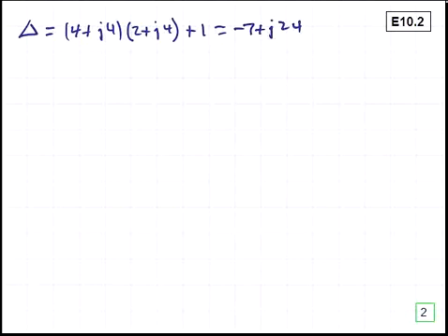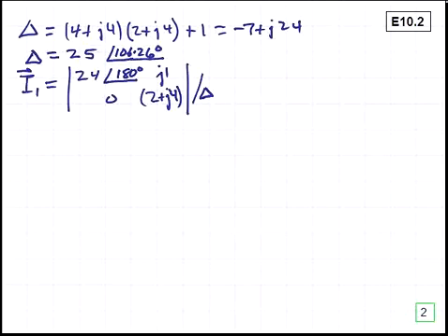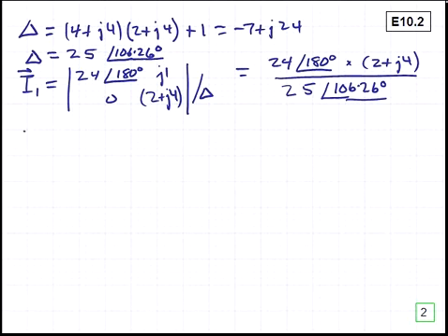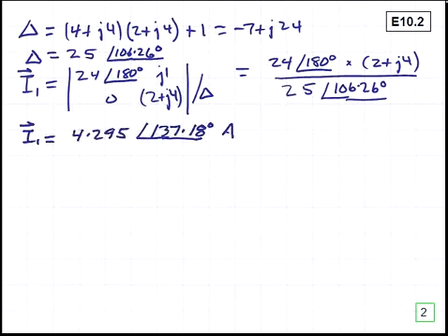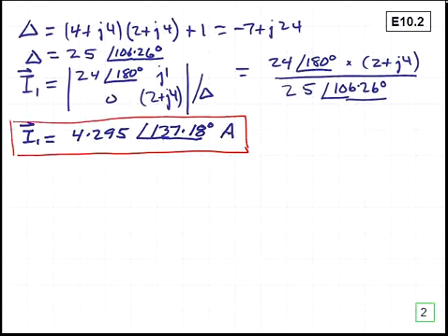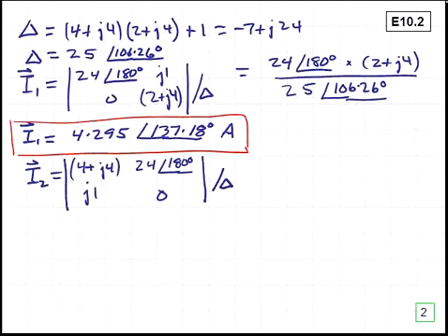The determinant of the impedance matrix, delta, is equal to minus 7 plus J24, or 25 at an angle of 106.26 degrees. Now we can solve for I1 equals... or I1 is equal to 4.295 at an angle of 137.18 degrees amperes. Now we can use Cramer's method again to solve for the current I2, which is equal to...